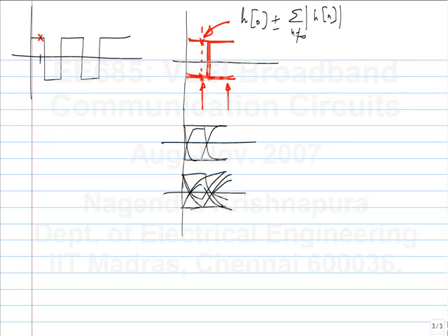This is typically what it looks like. If I look here, there will be some area in the middle where there will be no transitions, no traversal of the signal, and that part is the eye opening. If this is the sampling phase, then the values that you see on the y-axis correspond to these values. At least this is the range of values that you will see. You typically draw the eye diagram for a 2-bit interval, because at least then you don't know the timing of the signal. You cannot draw it arbitrarily.